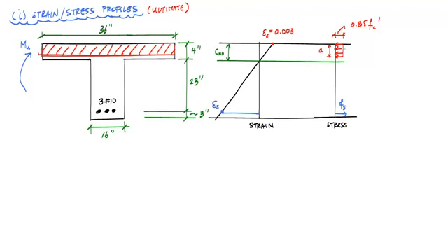This has a resultant force, I'll call that C sub C, and the steel has a resultant force, I'll call that T sub S in tension here. And there will be a centroid of this compression block, which will be this distance here, we'll call that Y bar, and the distance between the two, or the couple really, the tension and the compression forces, I'll call Z. And that's just another symbol for the arm right there. And really this comes out to d minus Y bar here.